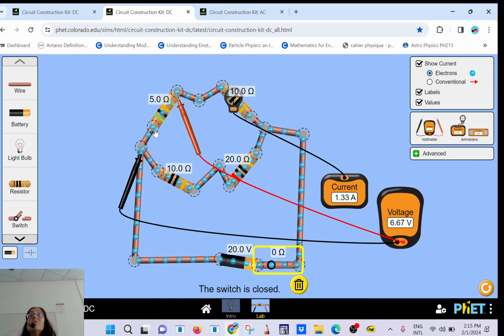If I want to find the terminal voltage, that 12 volts is called the EMF. This one is stealing 2.5. So how much is left for the load? So 12 minus 2.5, which is, what do you say? 8.5, right? 9.5, thank you. 9.5 volt.